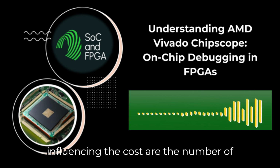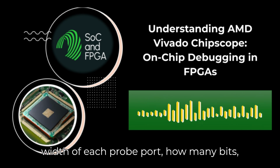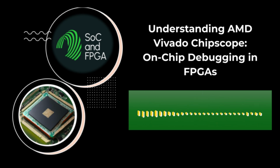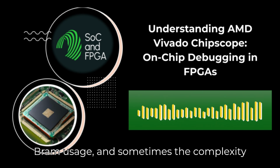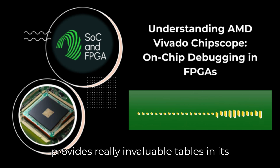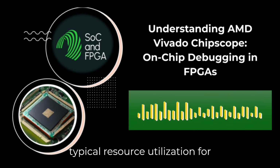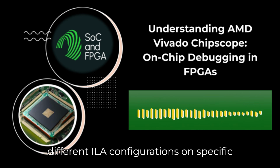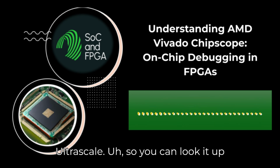The main factors influencing the cost are the number of probe ports you enable on the ILA, the width of each probe port, how many bits, the selected data depth, which dictates BRAM usage, and sometimes the complexity of the trigger mode configured. Vivado provides really invaluable tables in its documentation, for instance, showing the typical resource utilization for different ILA configurations on specific device families like Kintex 7 or Virtex UltraScale.